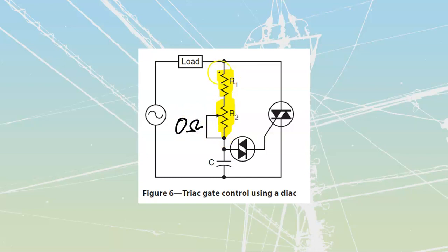And if they turn it all the way down to 0 ohms, we could get a ton of current flooding through here, possibly blowing this capacitor itself. So what we'll do is place another resistor in front of it. We'll just say this is a 100 ohm resistor in front of it. And by doing that, even if the customer adjusts this rheostat from 0 ohms all the way up to, let's say, 10k ohms or something, they can adjust anywhere inside of that range, but they're never going to be able to drop it far enough that there's no resistance inside of here.